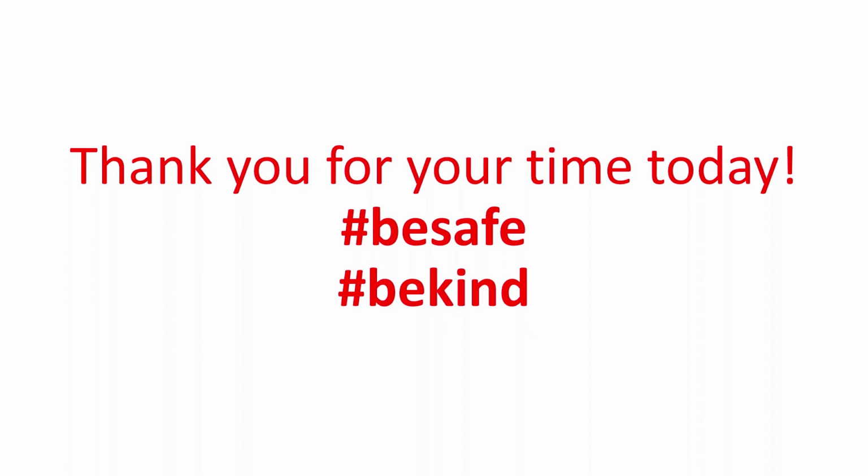When I'm 3D modeling, one of the things that you utilize are called dumb solids or AutoCAD solids, because they have no functionality. And you can use things like Boolean algebra, which is things like union, intersect, and subtract. But there's a fantastic little app in there called Trim Split. What it allows you to do is trim and split a protrusion from a 3D object away from the main object.